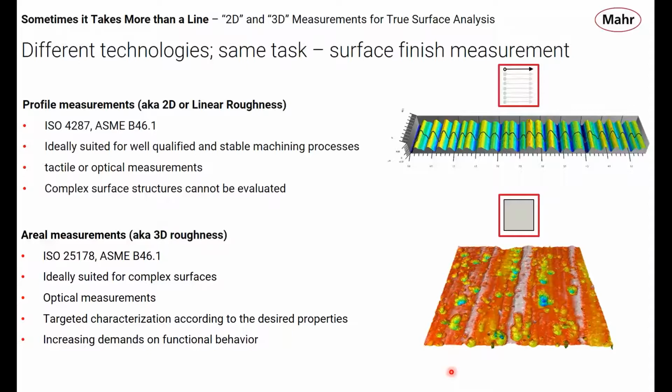As we've said, ideally suited for complex surfaces. Generally, these days, 99% of the time, 95% of the time, when we're talking about aerial measurements, 3D measurements, we're talking about optical tools. Yes, we can do it with contact stylus-based tools, absolutely. Probably not as fast, or effective, or efficient, but there absolutely are applications where we do that and where it's necessary.